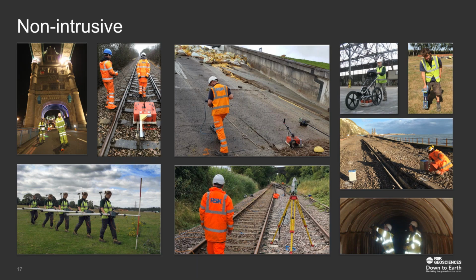The main applications of geophysics include identifying buried obstructions. For example, if you're expecting buried tanks, culverts, tunnels, or even buried concrete. I've seen this used before to identify buried concrete and their thicknesses on site without having to drill lots and lots of holes. Voids, whether these are man-made or natural, geophysics can help identify voids in the ground, for example, mine shafts, caves, solution features.